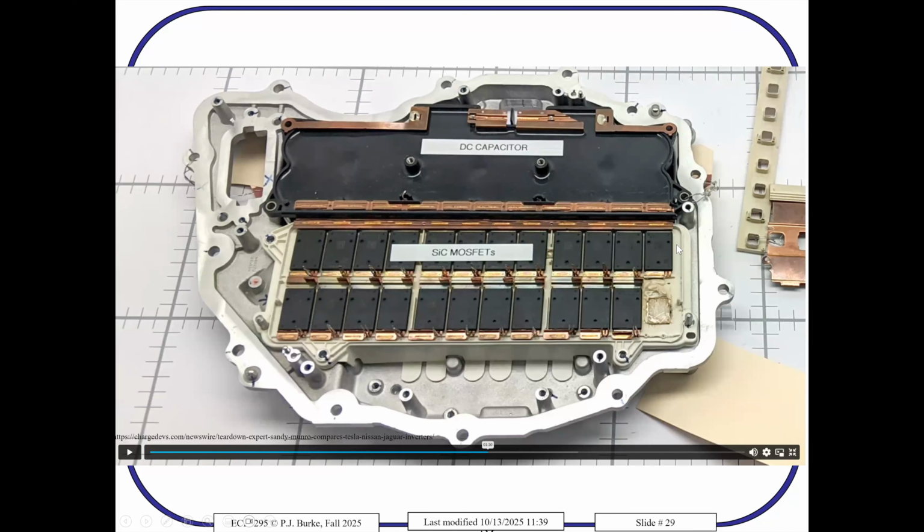And these transistors, when they're off, there's no current flowing, there's no power being dissipated. But when the transistor is on, there's a lot of current flowing. And we talked about the batteries for the Tesla being able to source 750 amps of current. So it's not a small amount of current that's flowing through these discrete transistors. And they're not perfectly efficient. So ideally, when the switch is closed, the resistance is 0. But when the switch is closed, the resistance is not 0. Let's say the resistance is 1 ohm. Imagine you have 100 amps flowing through a 1 ohm resistor. How much power is that?